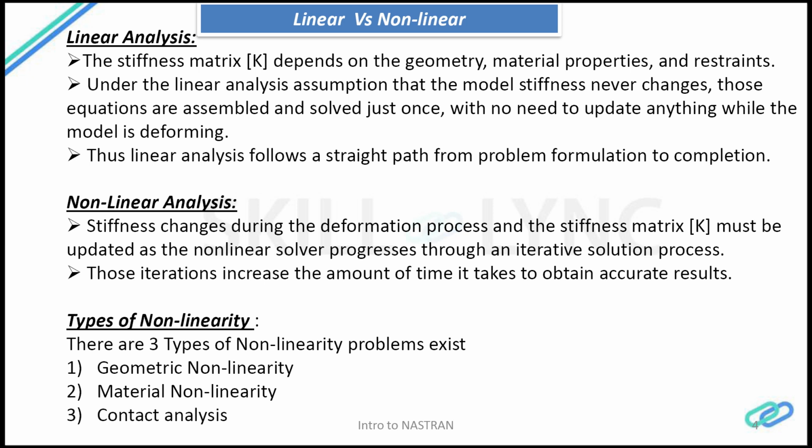The equations I refer to are the stiffness matrix equations in the finite element model, where the elemental stiffnesses and the nodal stiffnesses are assembled into a global stiffness matrix, which is solved once, and there is no need to update the stiffness matrix while the model is running. And most importantly, in the linear analysis, the stresses are in the linear elastic region.